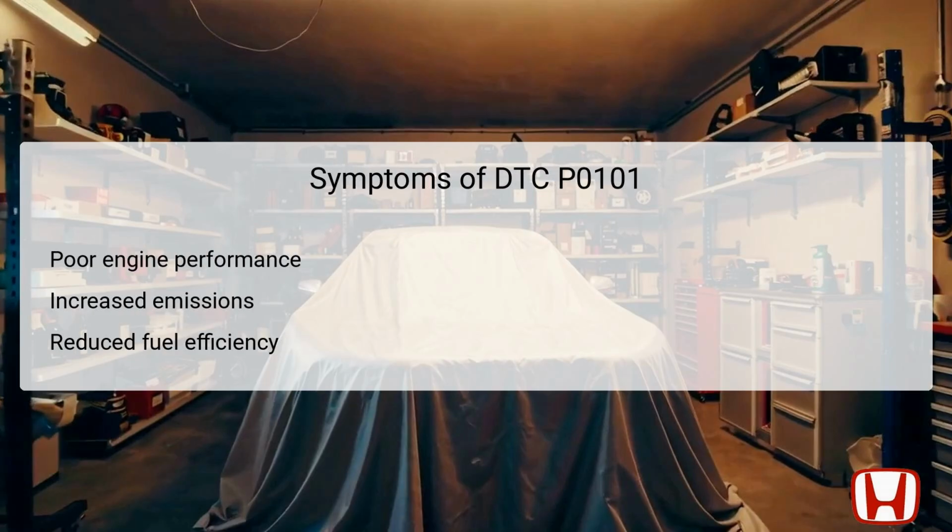The symptoms associated with DTC P0101 can manifest in various ways, reflecting the impact of MAF sensor issues on overall vehicle performance. One primary symptom is poor engine performance, characterized by reduced power or sluggish acceleration, often due to an incorrect air-fuel mixture being delivered to the engine.